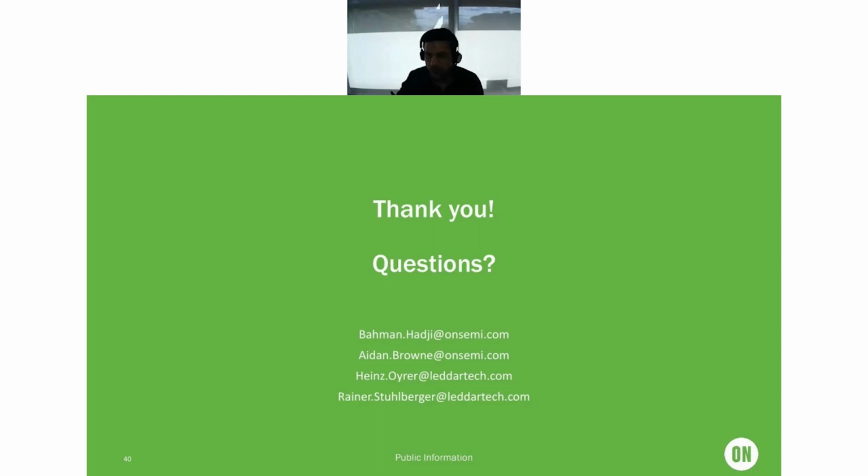Thank you, Rainer. Next, I'll also go to a related question on the topic we just touched on. Any eye safety issues with 905 nanometer laser? This is a common question. Of course, one of the differences between 905 nanometer and 1550 nanometer is that you can output more laser power at the shortwave infrared wavelengths due to the fact that it's absorbed in the eye before it hits the retina.